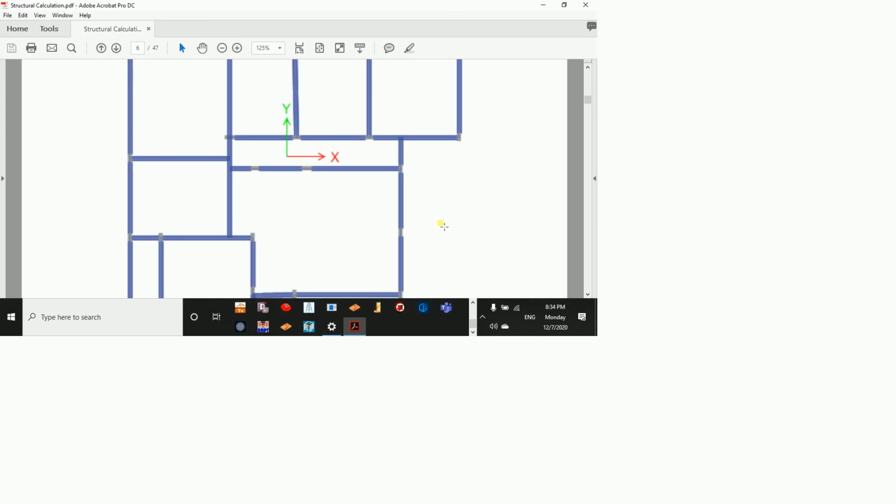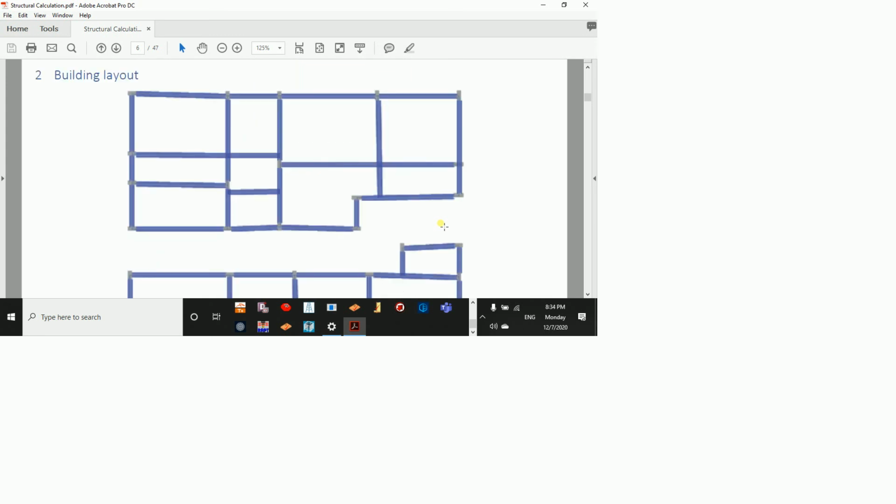Do you remember when I told you about the column being outside? See here, see how the column is available. Although the column shouldn't go outside, a lot of designers will somehow ignore the moment which is happening by considering that it is fully loaded. So they are taking the worst scenario, increasing a lot of reinforcement. And once again, that is due to the fact